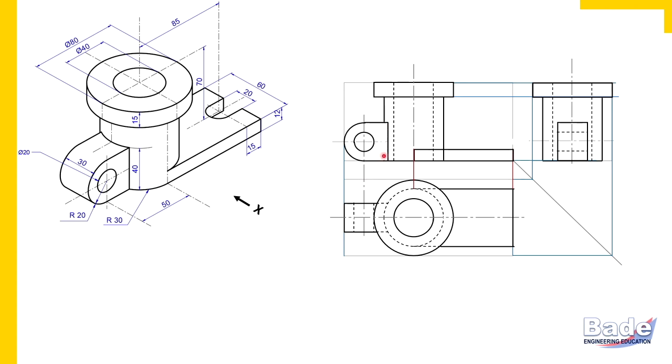It is to be erased if you have already drawn. So the same thing we are going to do here, watch here. This U-shaped block, that base plate is in contact with the cylindrical surface and it is exactly on the boundary generator. So the boundary generator inside the attachment is to be erased. Watch here, I have erased it.